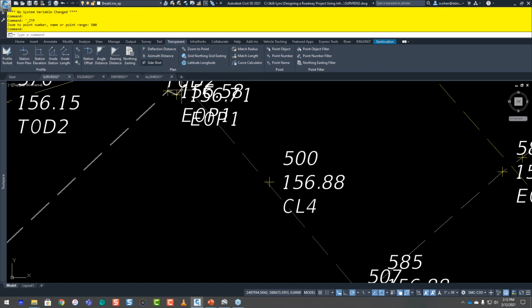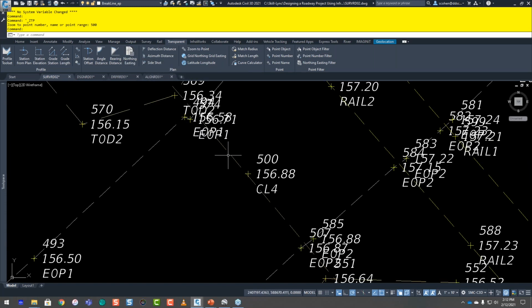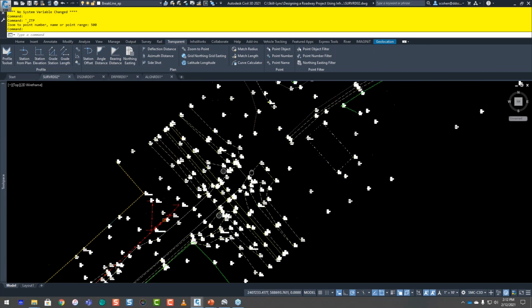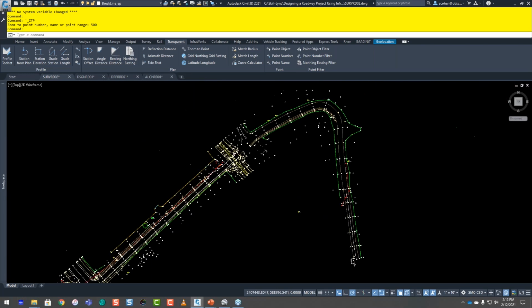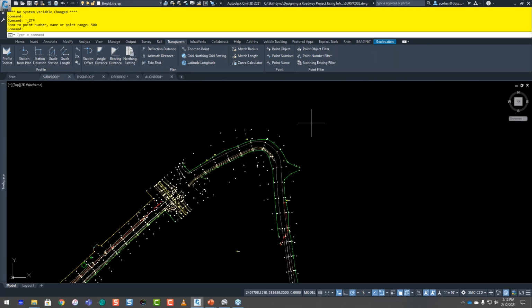So you can. It's very similar to entering it as you would expect. Okay. All right, so some of the other things, of course, if let's say you're doing a legal description, if I start the line command here, typically you'll have a point of beginning, so you'll click on a point of beginning. Then you'll have either bearing and distances, or angle distances, or azimuths, or deflection angles, or whatever, okay?